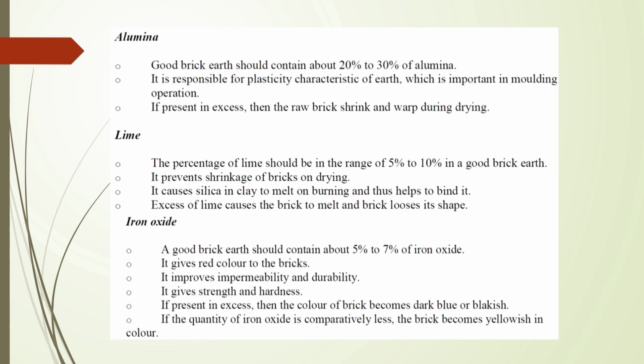Lime. A small amount of lime, not exceeding 5%, is useful in good brick earth. The lime should be present in a very finely powdered form only because even small particles cause flaking of the bricks. The lime resists shrinkage of raw bricks.